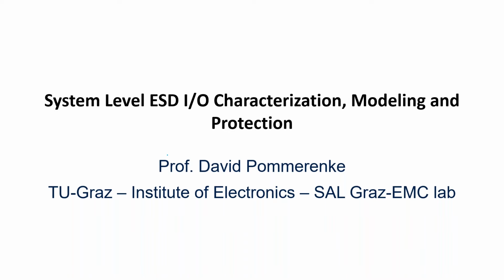Does a very small varistor provide a good protection, then the capacitance is usually very small due to the size of the varistor. But do you need quite a lot of protection? Then you need a big varistor, and then maybe this capacitance that is provided between the two terminals of the varistor is too big.